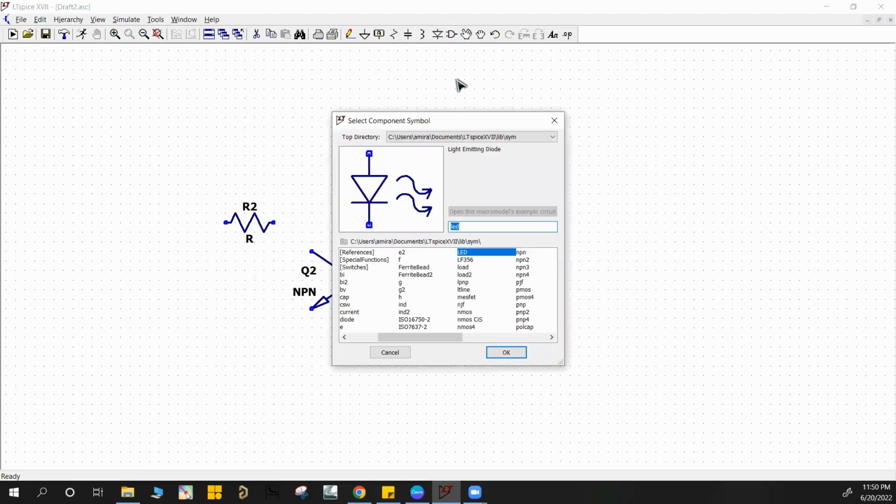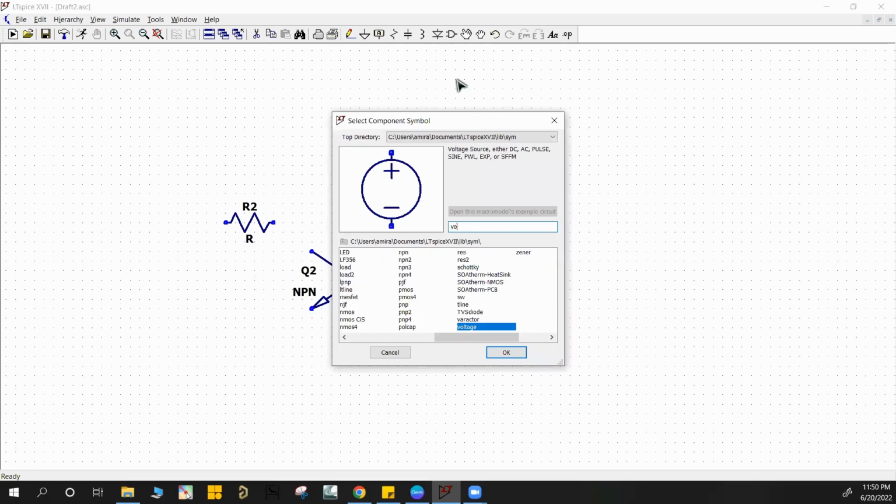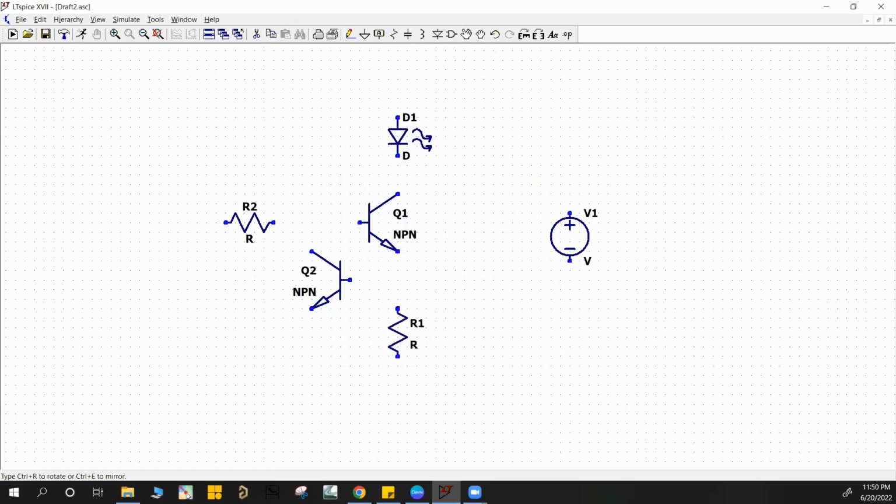You go to component and then you put, let's say I want a voltage source, right? So for a voltage, you just basically have this little voltage supply. You click OK, and then, again, same thing, it kind of hovers around, you place it here. Let's say we want to have 2, because we also have that MCU input to the base of Q1. And we also have ground.